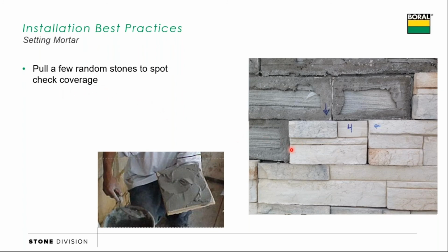An idea might be, especially if you've got larger crews or newer guys working for you, random check. Go through and pop a stone off every once in a while, every couple of hours, to make sure your guys are getting full coverage.